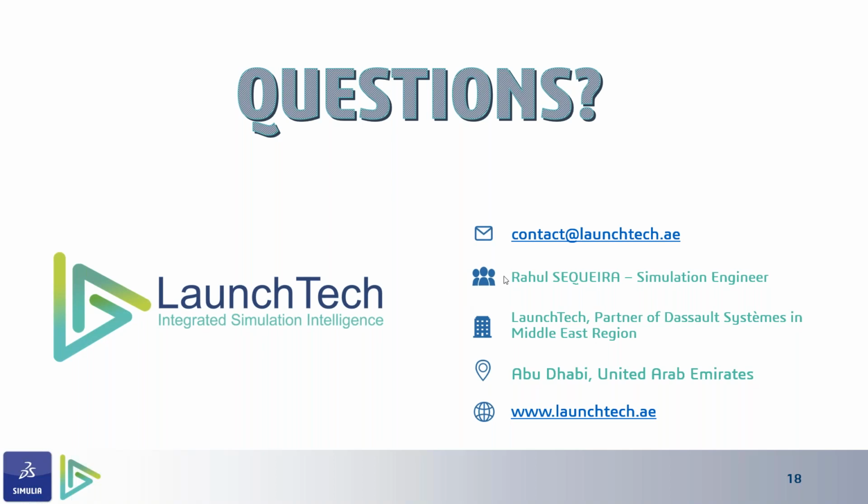Another interesting question I have: can the Abaqus calibration plugin predict the damage parameters for elastomer materials? No, not yet. There might be a plugin you could check within the knowledge base in order to understand the damage parameters. You could drop an email again to me so that I can give you relevant links. However, mostly for damage, it's usually done using the default damage parameter options that are available within the Abaqus material database.